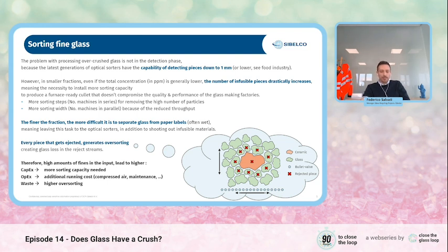These machines, every time they are expelling an object, are creating oversorting, they're losing glass. In the picture on the bottom right of the slide, there is a nice example: to eject one piece of ceramic, the red particle surrounded by green glass particles, the valves will open, 1, 2, 3, 4 valves in series, for a certain period of time, which is the vertical arrow. And just to hit one ceramic piece, we will discard all the glass pieces around. So for every fine piece of ceramic that we hit, we might be losing 10, 15, 20 pieces of glass around it.